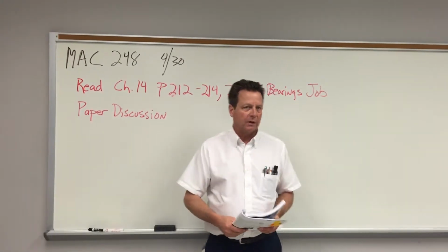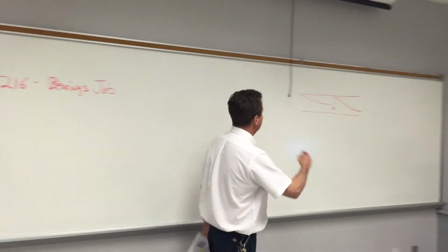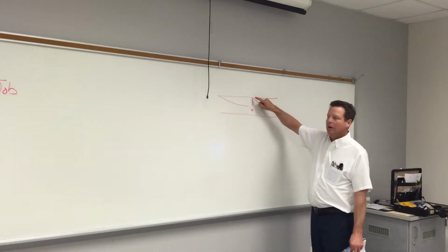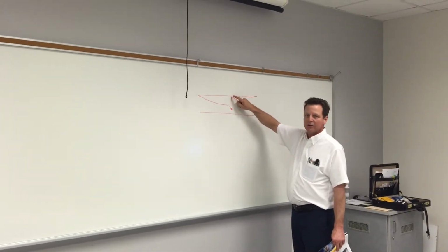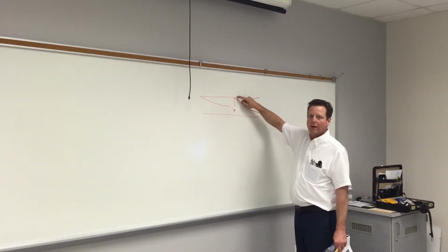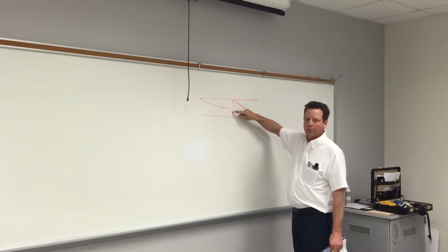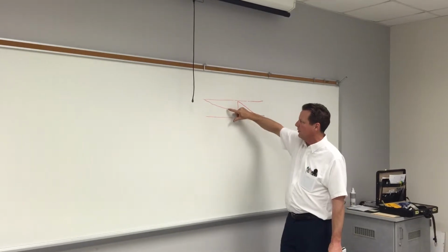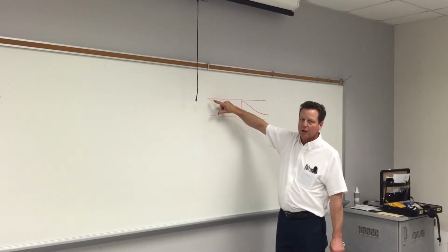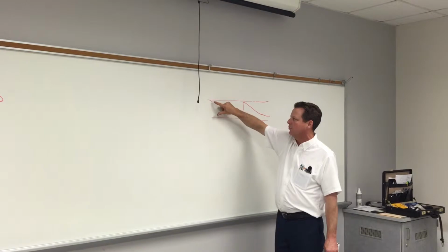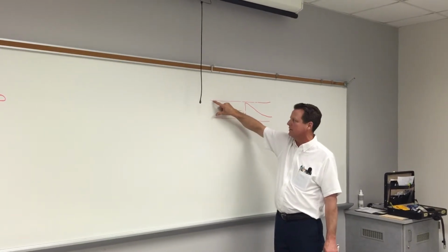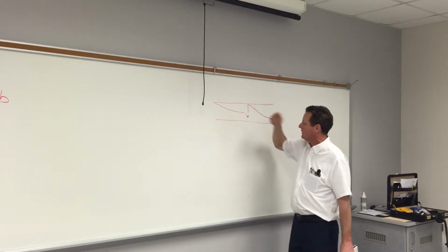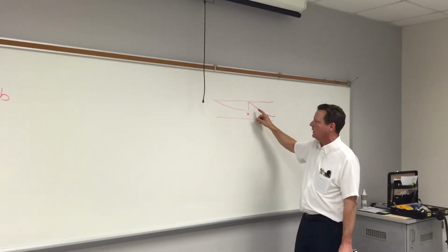Control charts is how we use that. I gave an example here of a tool wear application: as the tool wears out, we then change the tool. We go back to our wear offset and try to get our process back in the middle of the bands. Then as we do the production run, the tool starts wearing, and we start coming up to being a bigger diameter that will be outside of our tolerance limits, and we do the process all over again of changing the insert.